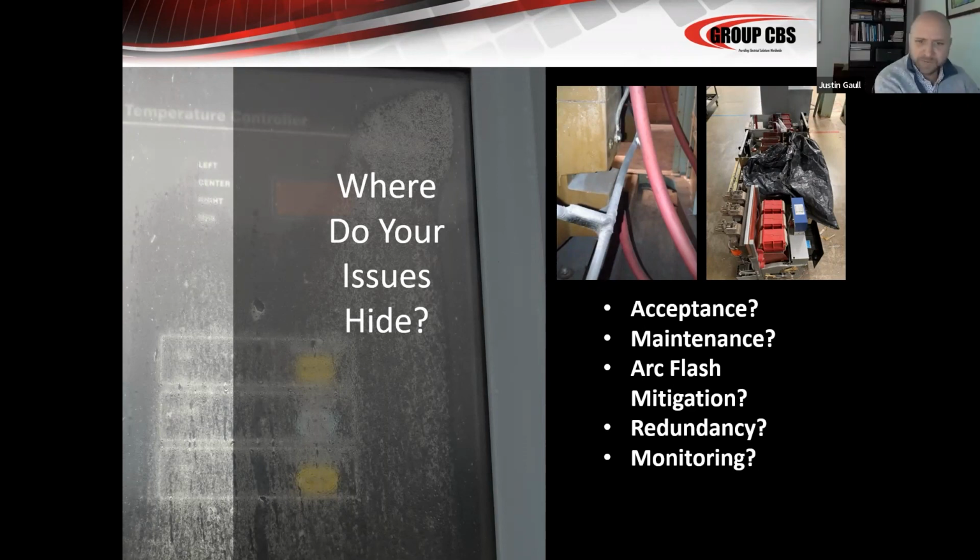Paul says we typically high current test the 480 volt power center breakers every scheduled maintenance outage. It's at a power plant. The breakers are also fluffed and buffed each outage, tested at 4 points along the curve, and if not within spec, they call in a design engineer. Also, we utilize zone interlocking on the 480 volt power centers to reduce arc flash incident energy, and this was before the fiber optic systems were readily available.